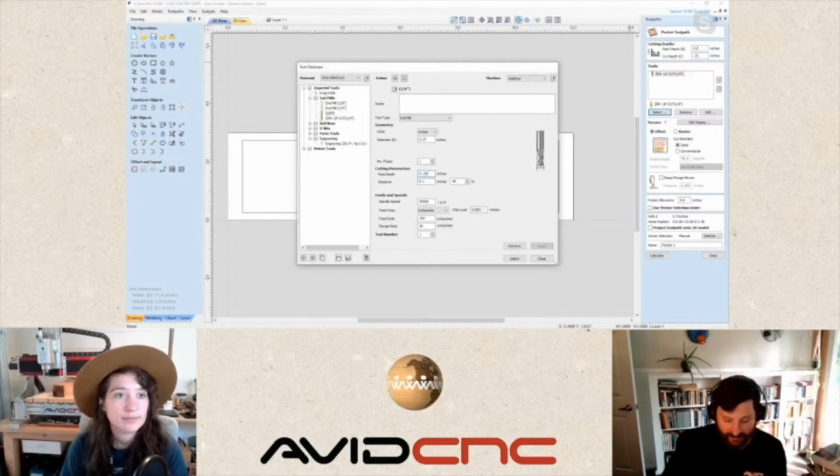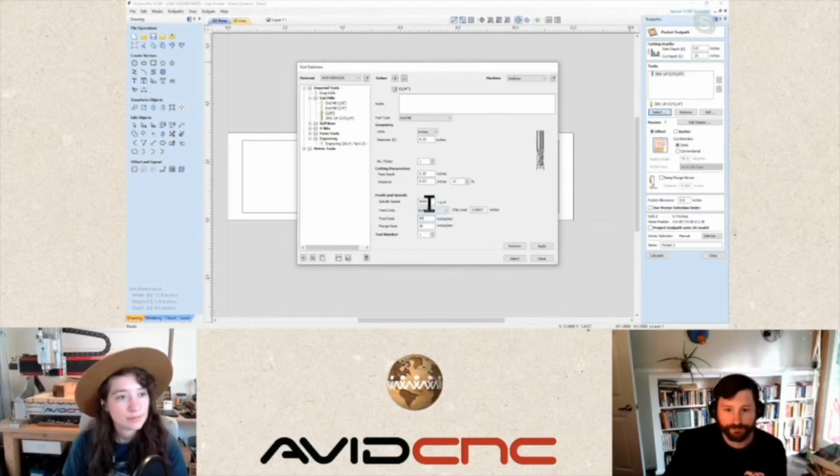0.25 inches. 0.25. I sometimes put twice those points, and we're going to do a step over of 0.03. And so this is just about a 12% step over. And again, we're going to slow our feed rate down and our spindle speed down because we want achievable feeds and speeds when it comes to setting up our machine and to get that proper chip. We want to calculate these chips with feed rates that we can achieve, right, Sami?